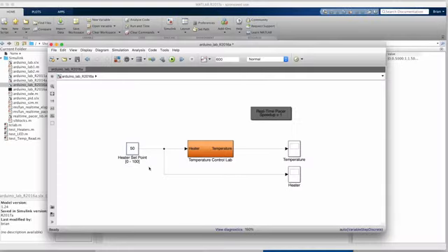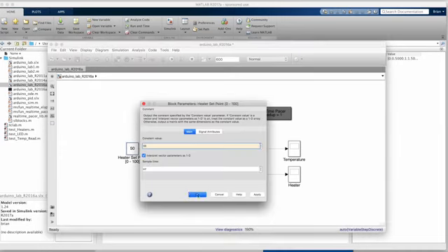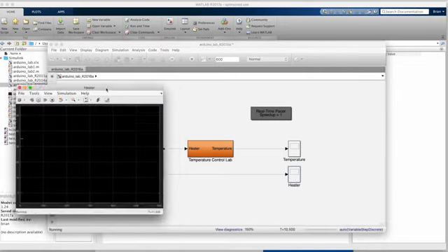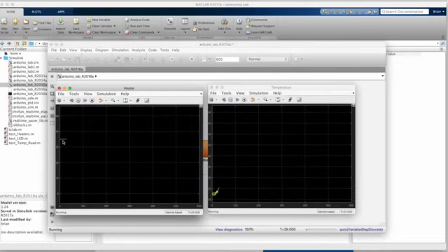For this first test, I'll set the heater open loop to 35%. This will be a step input from 0 to 35, and we should see a step response from our hardware that starts at room temperature and rises to some steady state temperature. Now, temperature doesn't change that quickly, so I ended up running this for about 10 minutes. I'll speed it up and spare you the time. Notice the shape of this response. It increases quickly at first and then tapers off to about 55 degrees by the end.